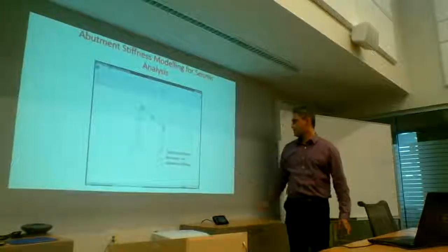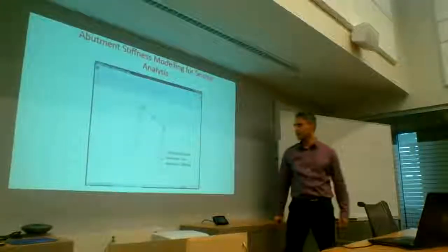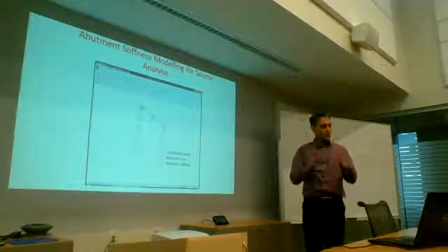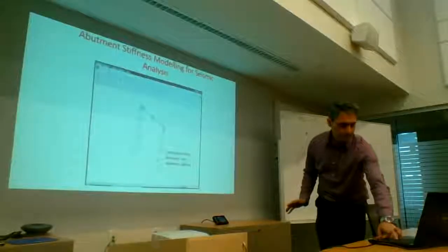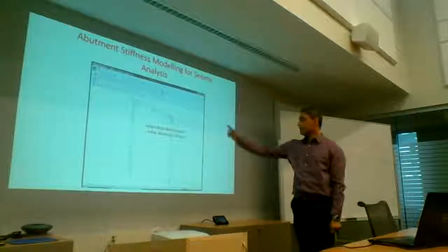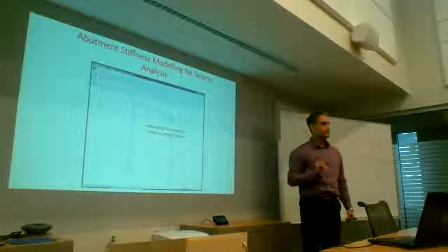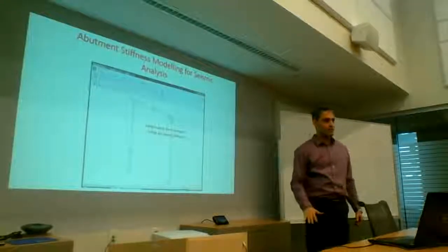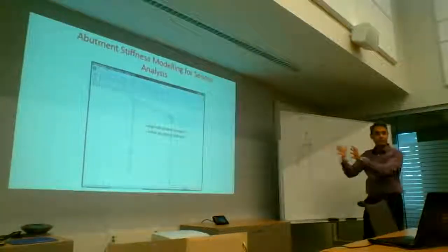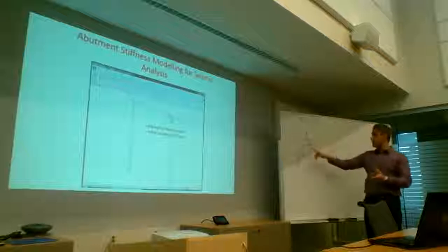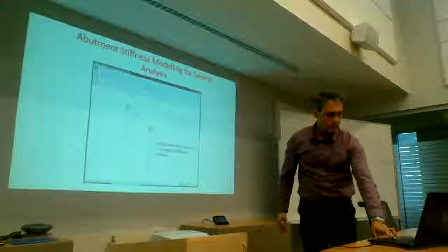So these are the bending moments. So you look at this. This is about 13,600 kilonewton meters of the column demand at the base, without having any abutment stiffness. Okay? Now, when I go with the initial stiffness, it drops from 13,000 to about 2,000, a factor of 7 drop. But that again assumes that your backfill and the diaphragm can generate about 6,000 of this instead of 1,400 or whatever. So that's not realistic.